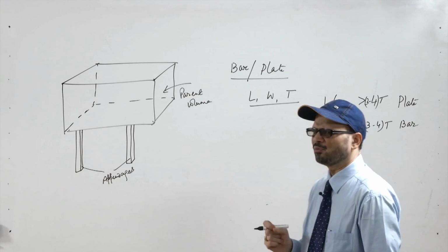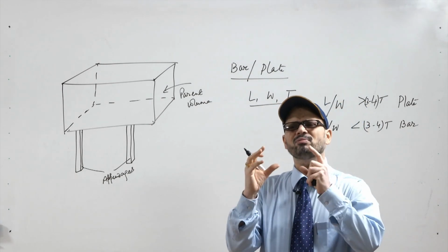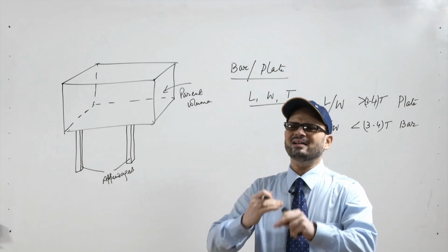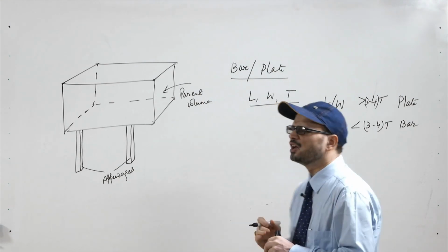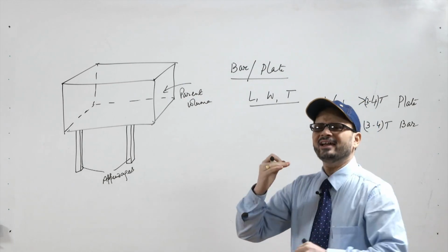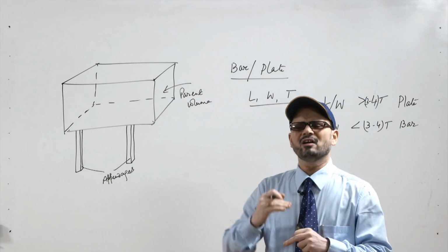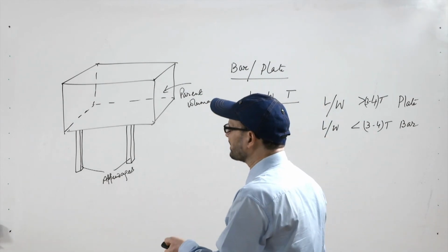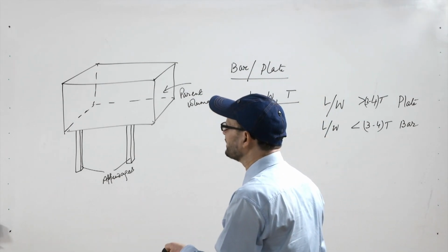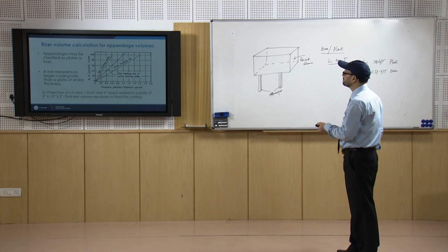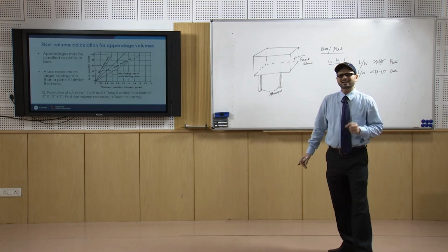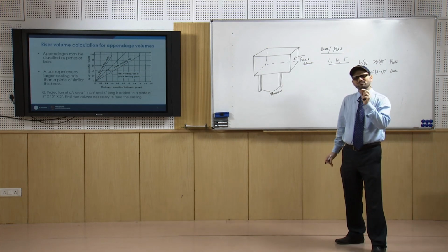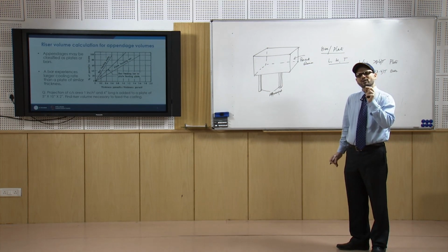Normally, in the case of a bar, it has 4 effective surfaces from where the heat extraction takes place. So, the larger area exposed is there from where the heat transfer can take place. That is why a bar experiences a larger cooling rate than a plate of similar thickness, and that is why a bar requires a smaller amount of feed metal to account for the shrinkage.